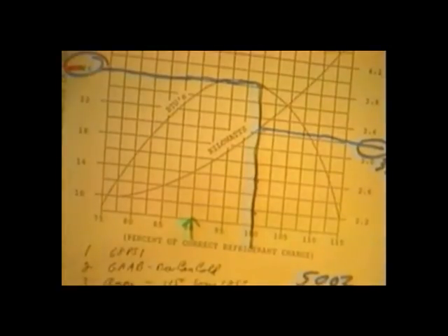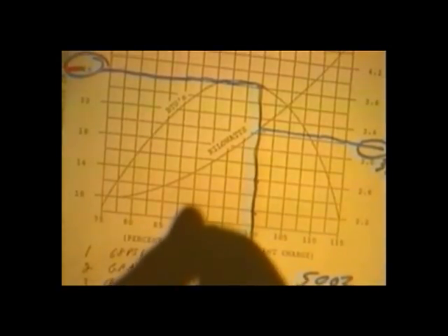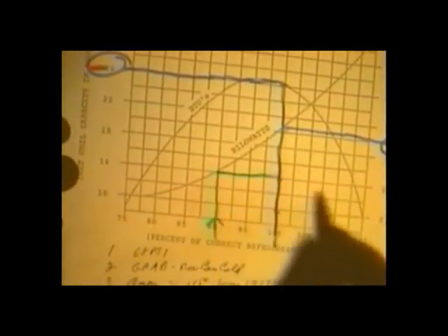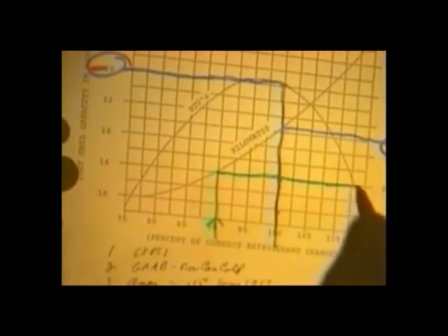So watch this. 10% undercharge. It's only got 45 ounces in there. And didn't I tell you before that the charge is critical, plus or minus 2 ounces? Let's see what happens with 5 ounces undercharge. So we'll come up here to the kilowatt line. Watch this. Here we go. All the way across. Look at that.